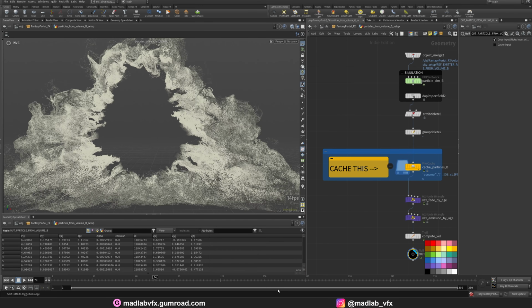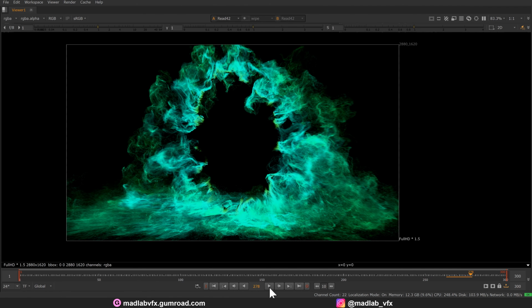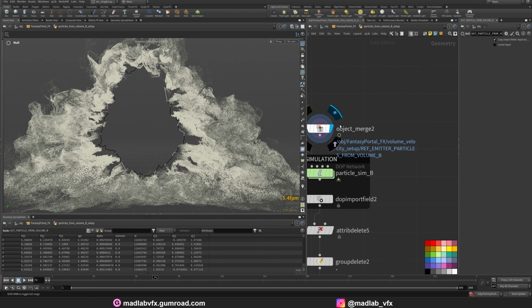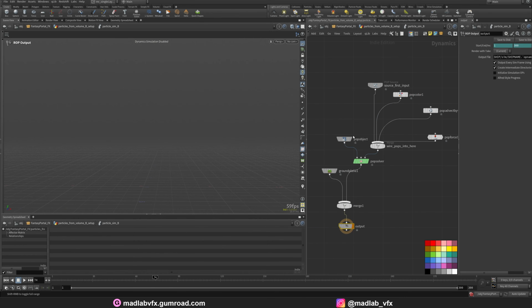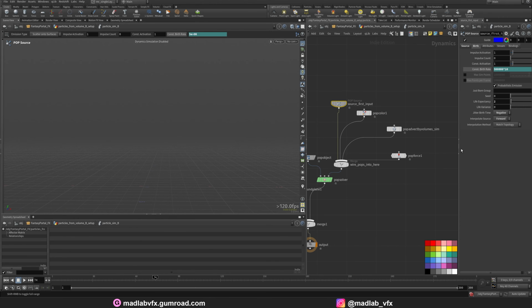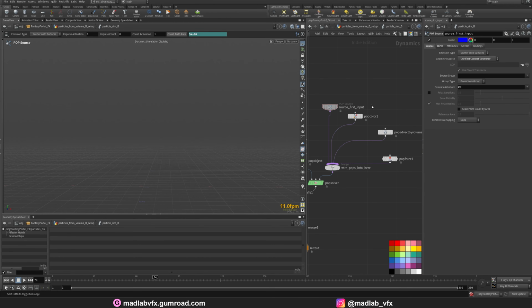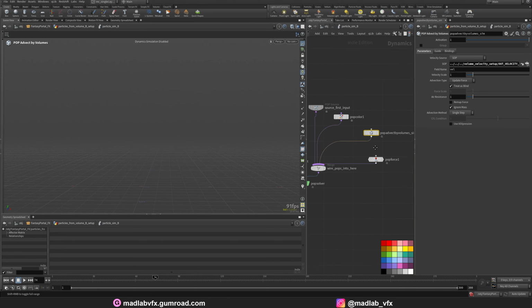That's the big one. Here in the Nuke, we can see that's the big particle. We are going to analyze that. Again, just use the outline. Inside the particle simulation, it's pretty simple: the source with a life expectancy of 2. Emission attribute Cd, using pop color just to drive the alpha based on the age.